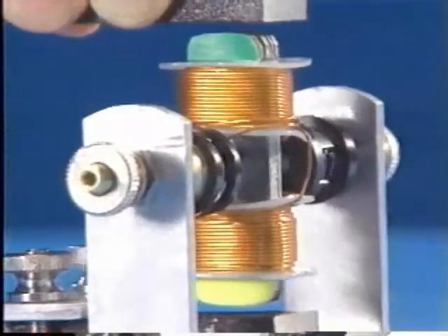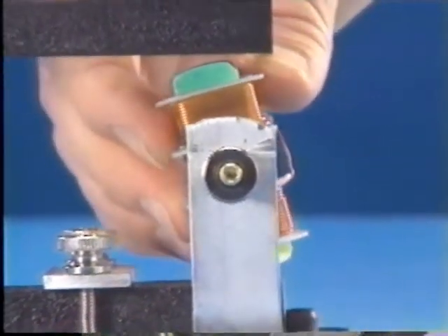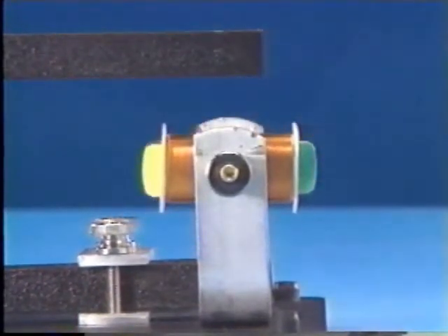Although it'll be stopped in certain positions, you must remember that in order to generate AC, the coil is constantly spinning. As the coil revolves through the magnetic field created by the 2 magnetic poles, it cuts through the flux lines at different angles. To start, the coil rotates to a horizontal position with yellow on the left and green on the right. This graphic shows that for this instant, the coil is positioned parallel to the magnetic lines of force as represented by the arrows. At this point, no voltage is induced because the magnetic field is not being cut.